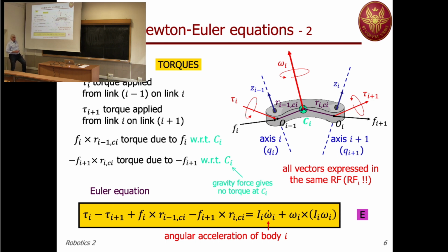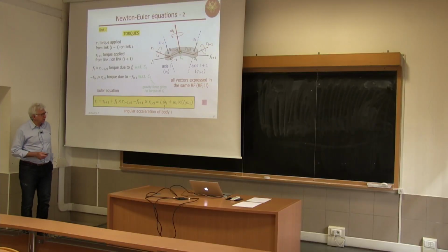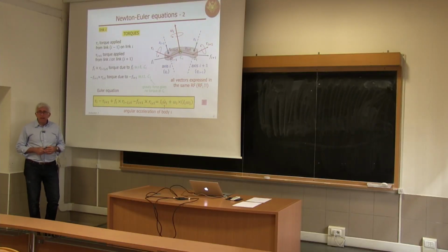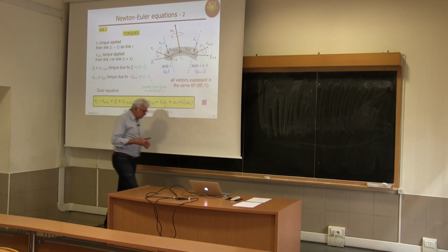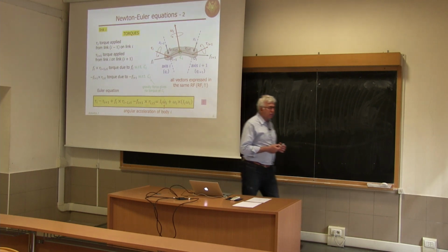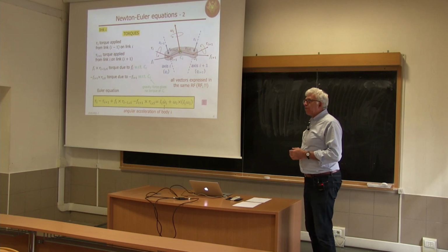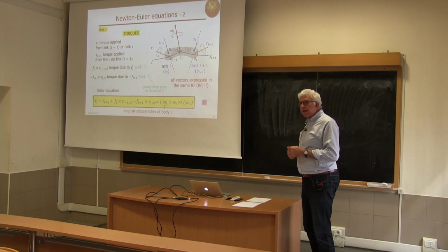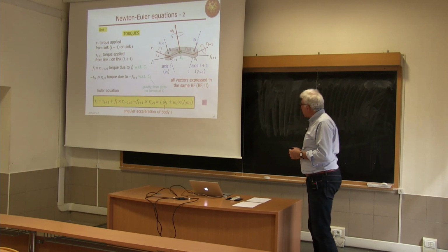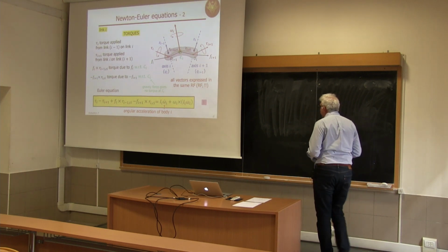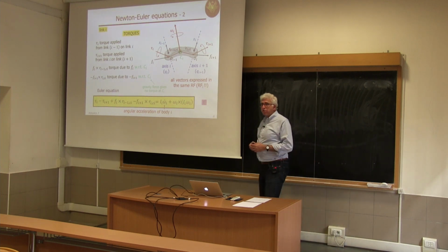Now, in the two equations, we have acceleration quantities, the angular acceleration omega dot I, and the VCI dot, so the linear acceleration ACI of the center of mass. So if we want to use a recursive formalism with moving frame, we should be able, just like we did for the linear and angular velocity for the algorithm for computing recursively the kinetic energy of our system, of our manipulator, we should set up recursive equations also for that.